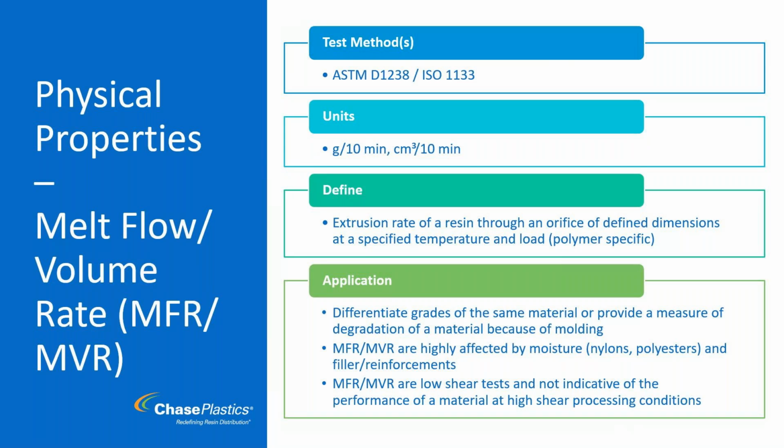So same with stuff like TPOs. We take a propylene and we add in a low temperature, low Tg rubber to it. Same with nylons. When we impact modify them, the low Tg impact allows the molecules to move at those low temperatures, or continue to move, I should say, to allow them to absorb the impact. So ABS, TPOs, anything really that has the rubber in them will allow for better low temperature impact performance.